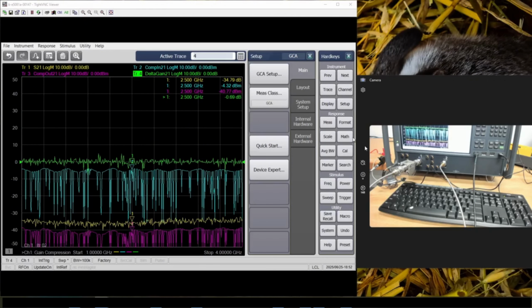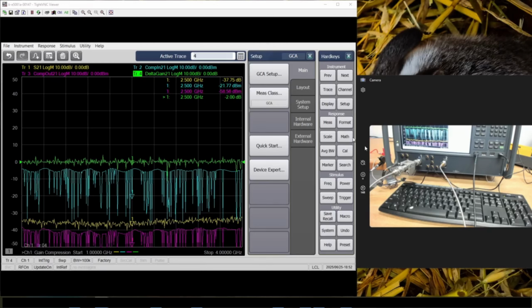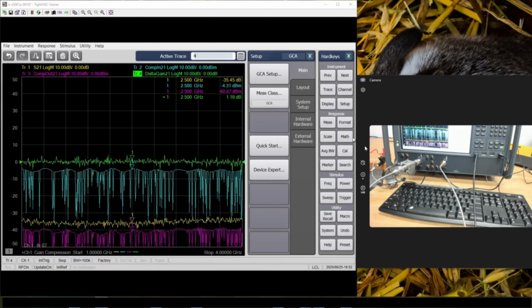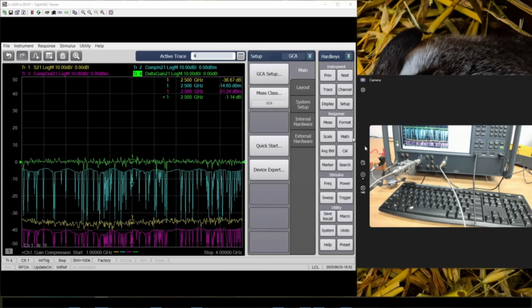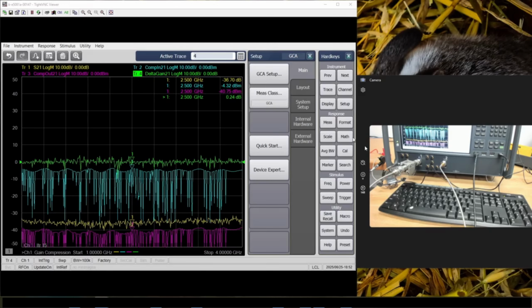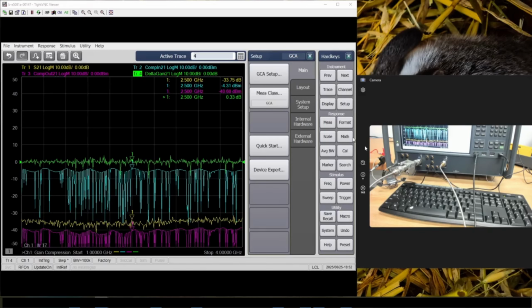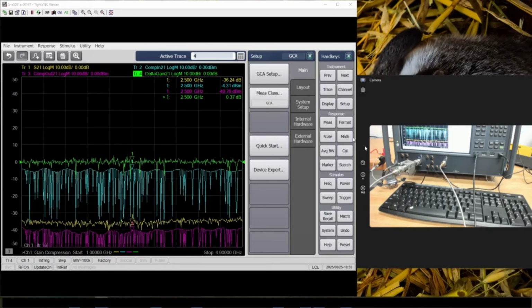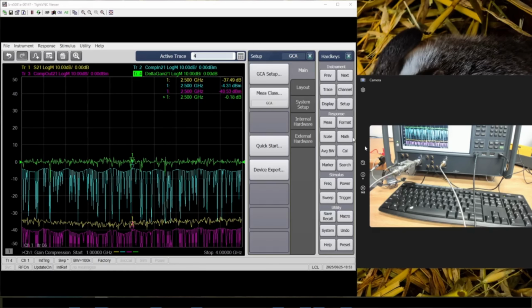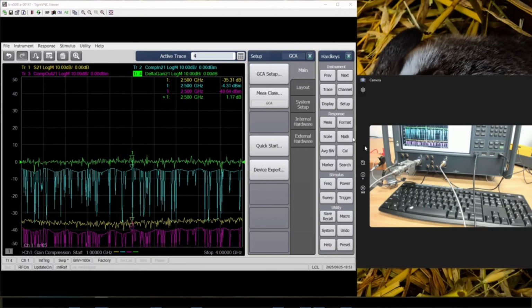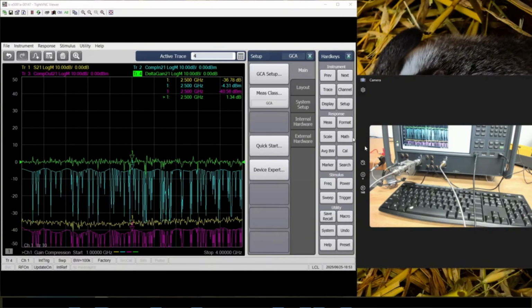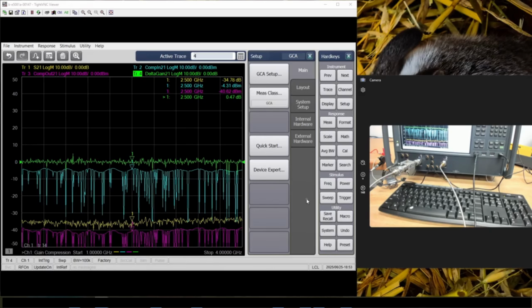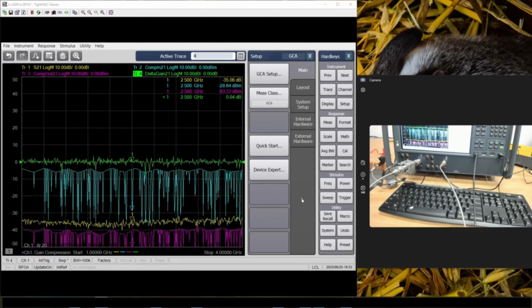So that's the theory, and with this software we are able to determine across a frequency range instead of doing point by point measurements. Without this software you can still do it, but you have to stop at every frequency point, for example 1.5 gig, and then you vary the input power. Then you determine the region where the output power doesn't tally with the input power in terms of changes. This is a pre-setup I've done, but I'm going to walk through the beginning step by step again.